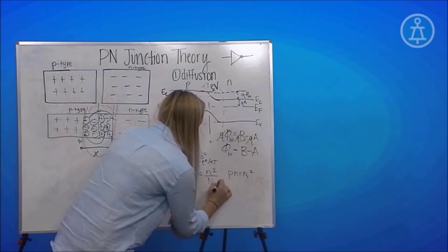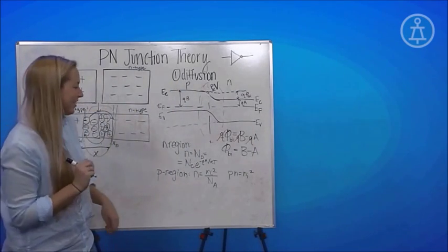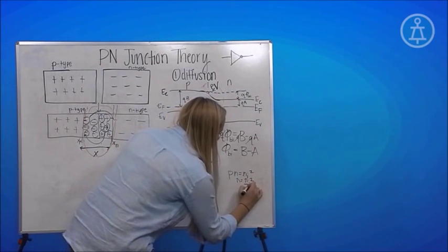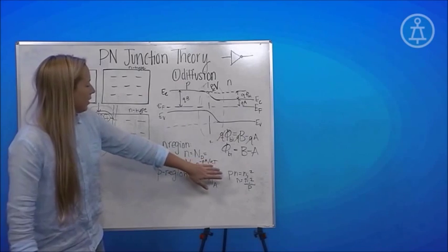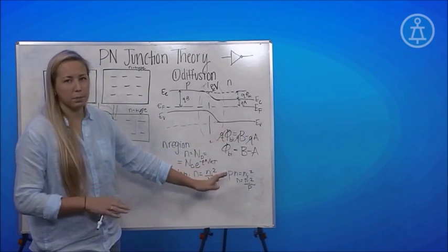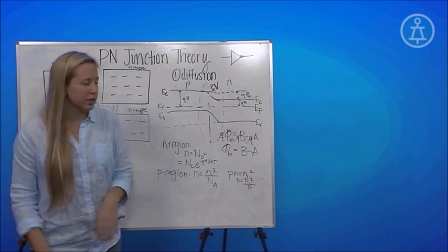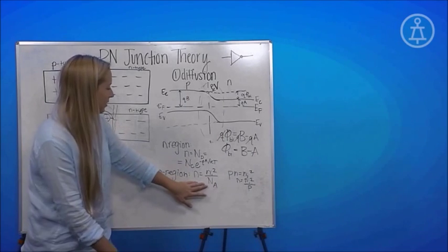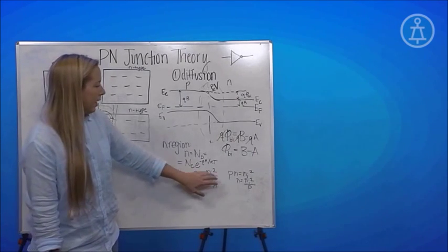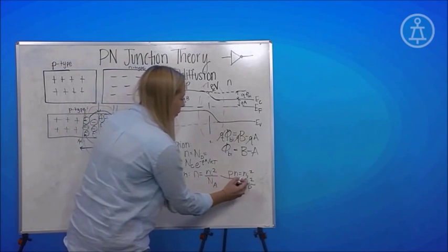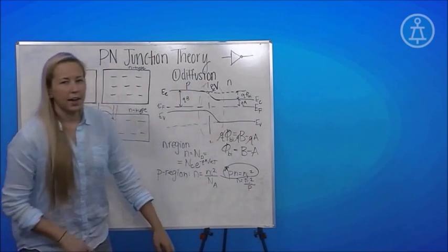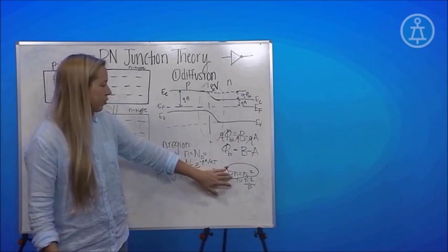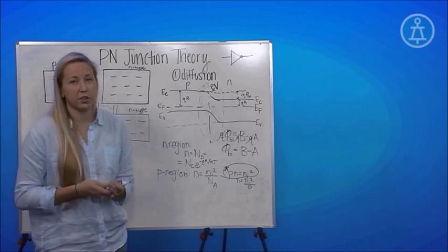Okay. See how you double check? I caught myself. So, since it is a p-type material, which means that it is doped with acceptors, we can say that our concentration of holes is assumed to be the same value as the number of acceptors. And so from this golden rule, which you should have memorized by now if you don't already, the concentration of holes times the concentration of electrons is equal to the intrinsic value of the material squared.